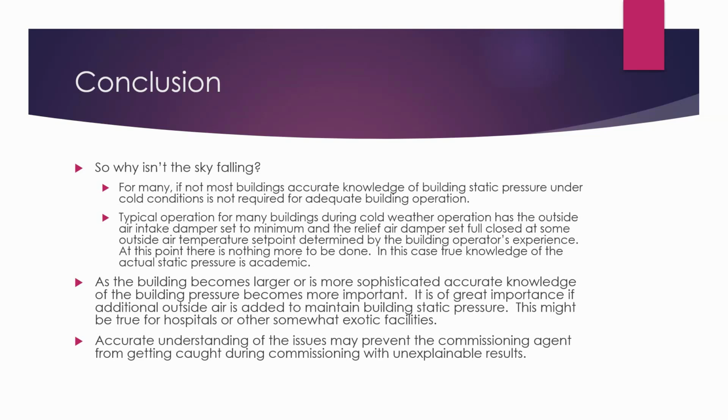So here we are, we've talked about this thing for this last hour, and for many buildings, it's really not that important. However, as the building becomes larger or is more sophisticated, accurate knowledge of building pressure becomes more important. It is of great importance if additional outside air is added to maintain building static pressure. This might be true for hospitals or somewhat exotic facilities.